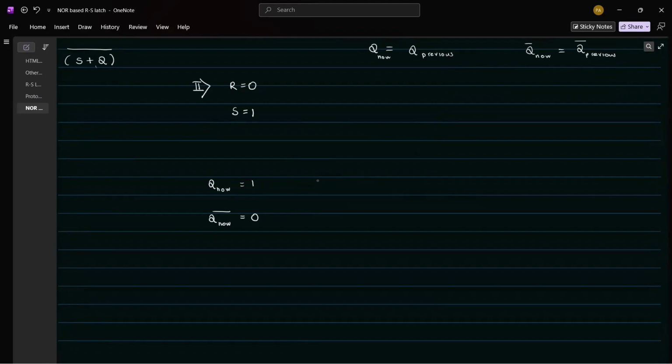I'm going to teach you a short circuiting method for NOR gates. For NOR gates, we know (a plus b) whole thing bar is there. If x is equal to (a plus b) whole thing bar, if either one of a or b is equal to 1, x must be equal to 0.